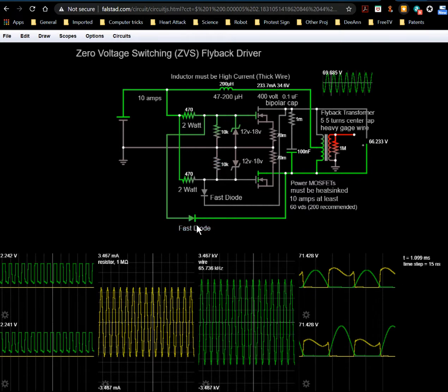And by the way, you could probably actually use just regular 1N4007 diodes, as long as this thing's not going to run at more than 10 kilohertz or so, because they'll operate just fine, typically at those levels. But you're not dealing with a lot of current, because all you're doing with these diodes is not just trying to drop power across a resistor.